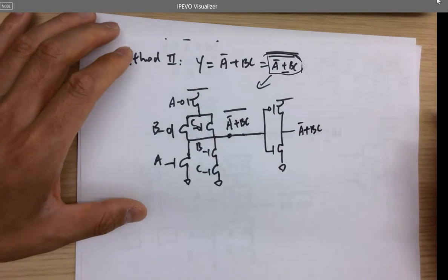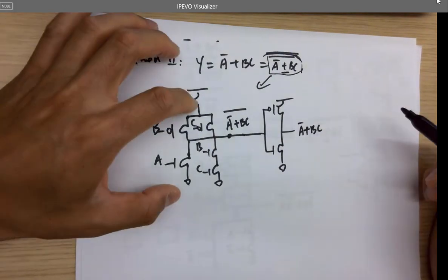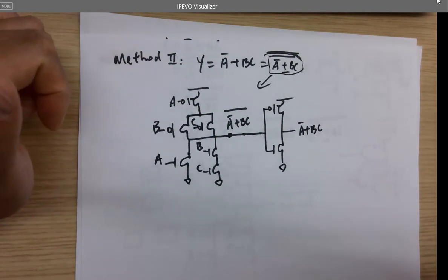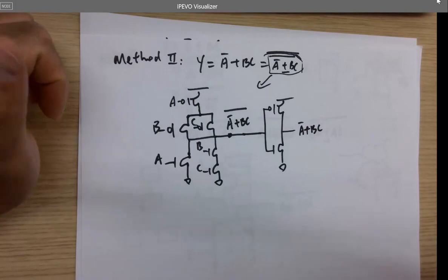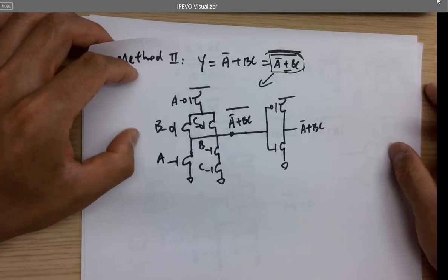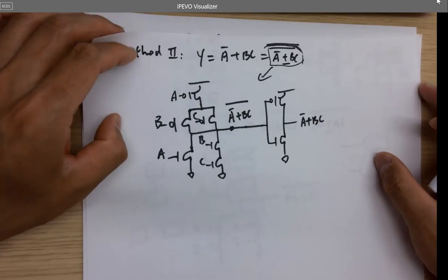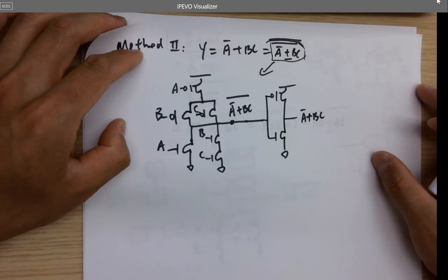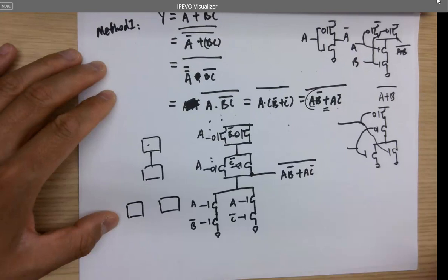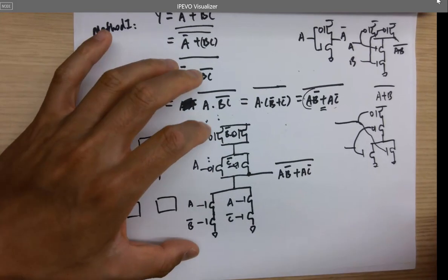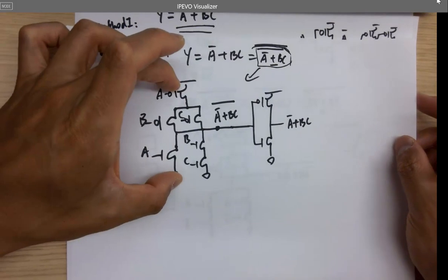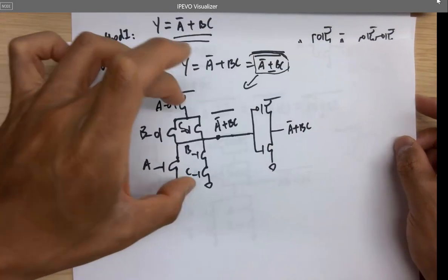How many transistors do we have in this circuit? Still 8. But it's less integrated. If you do the layout, you'll be able to find out they could be slightly different. The reason for that is when we manually lay out this guy, we can probably just draw one stick. But for this guy, you have to do one stick for this one, then put an inverter afterwards.